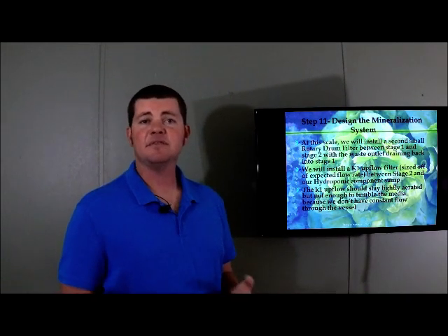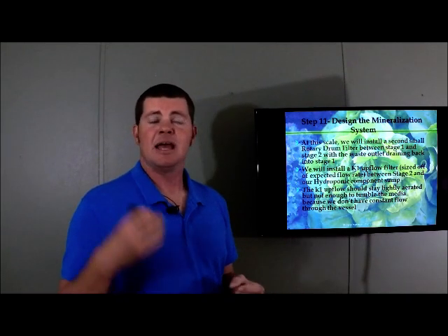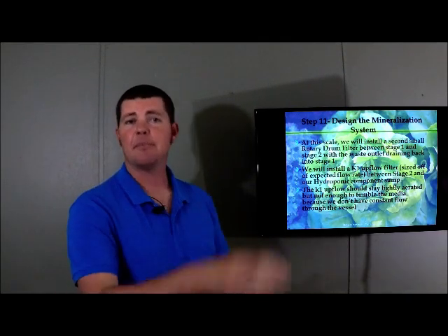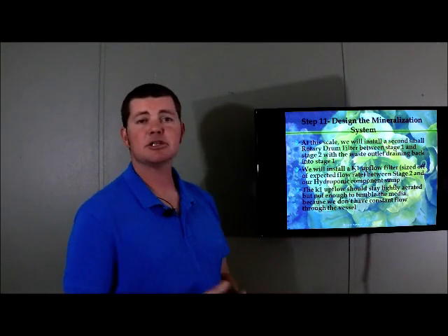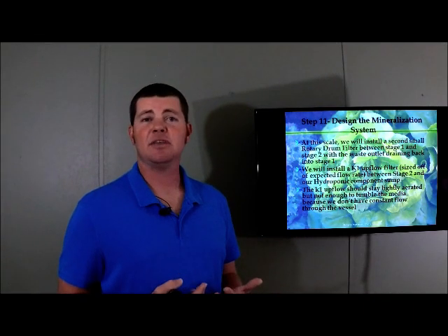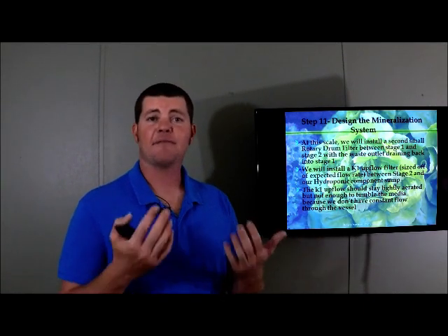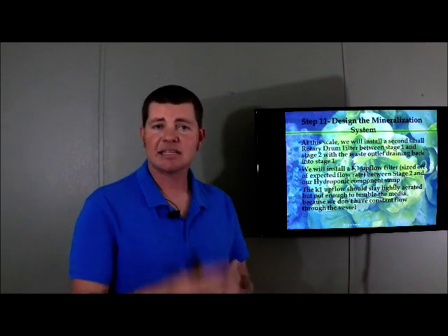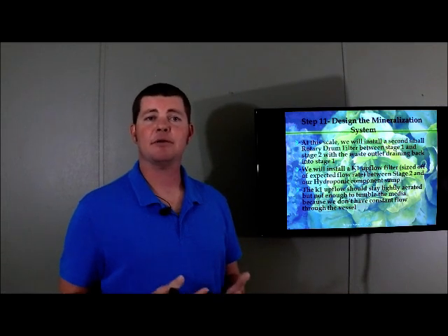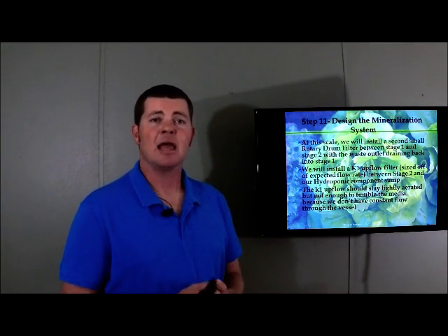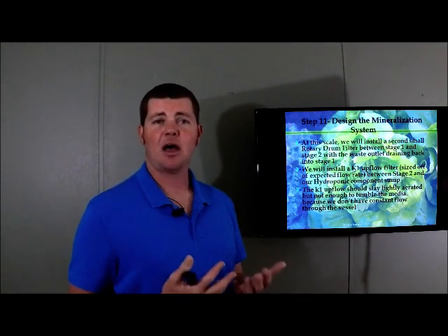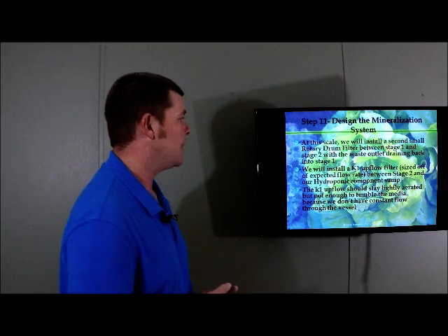On the other side, you could have 15 small K1 upflow filters dedicated right there to each greenhouse and have the water flow through that before it enters the sump. And this is to polish any excess waste that was delivered to stage 2 and to polish any of the biofilm that comes off of the biomedia, because it's constantly creating new bacterial spots, and because of the abrasion in that biofilter, the second stage of mineralization, it's knocking off sloughs of old, dead, dying bacteria. So to catch those flocks, you use a K1 upflow filter.